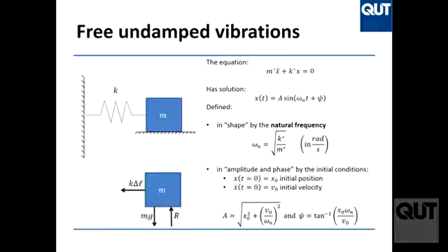What's amplitude physically? If this thing is vibrating, what does A tell me? Exactly. How much it vibrates one side and the other, maximum. Like what are the limit points of the vibration? That's A. Is it important for engineers? I'll tell you that out of these three parameters, two are the most important. The other one is way less important. Is A one of the important ones or not? Why is it important?